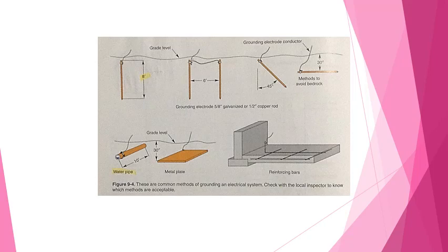Proper grounding of electrical systems is required to, 1. Limit the voltage entering the system from surges in power from the supply transformer or from lightning, or 2. Hold all parts of the electrical system, including non-current carrying enclosures, at 0 potential to ground.